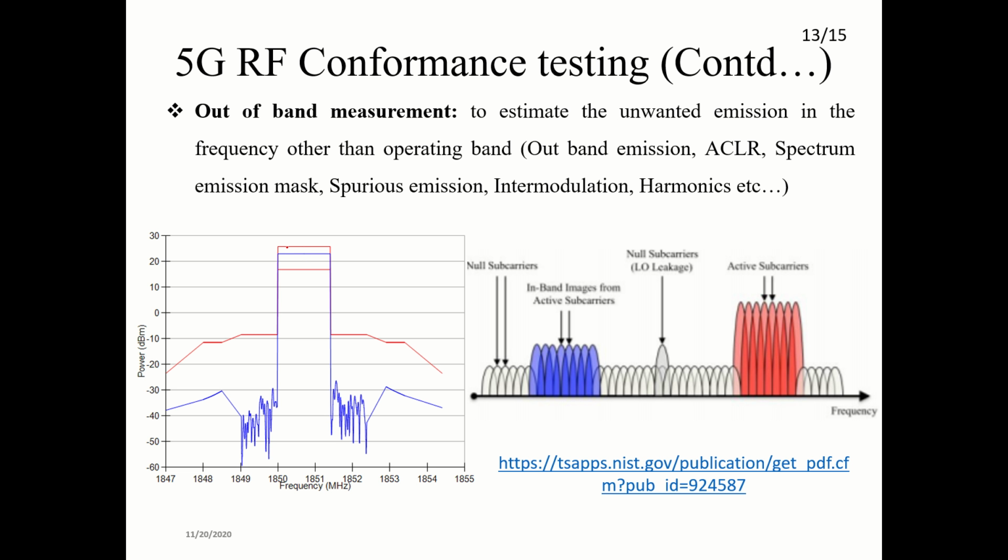You can see here, this is the desired band, but you have a mask here. The adjacent band frequency spectrum should be within this limit. Otherwise, if it goes beyond this, it will create a problem for other operating devices. Now the spurious response, for example, you can see here.